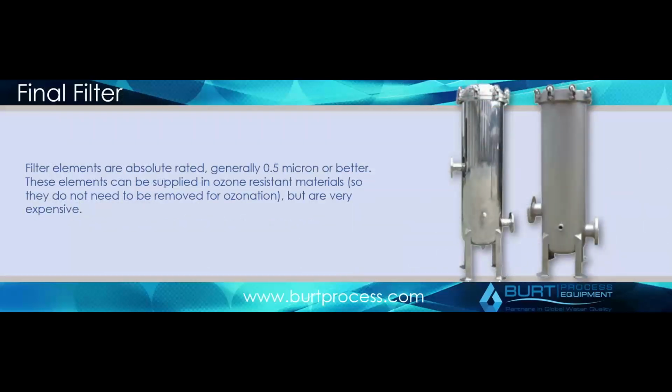Finally, downstream of the DI as well as the UV, you have your final filters. These are generally 0.2 to 0.5 micron, and they're designed to remove endotoxins. Endotoxins are basically the biological residue left from the bacteria destroyed by your UV. The filters also serve as a final catch for anything from your resins that may be coming out as part of your distribution or recirculation loop.